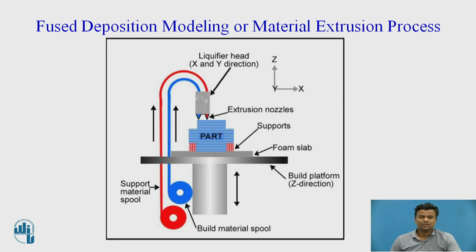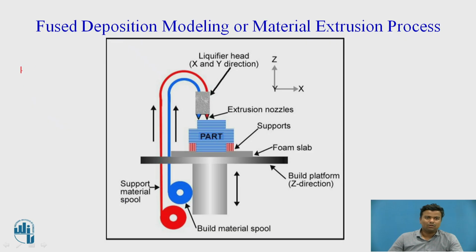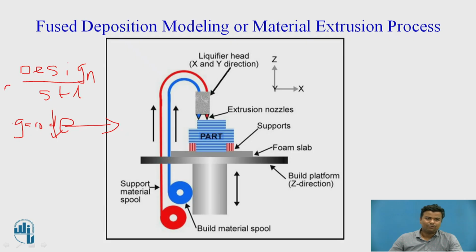In the last session, we discussed what is meant by additive manufacturing. Additive manufacturing is a process that starts with a design. We save it as an .stl file and provide it to different 3D printers. The STL file will be converted to G-code by slicing the CAD model. The design will be in the form of a CAD model, and the CAD will be converted into a prototype.